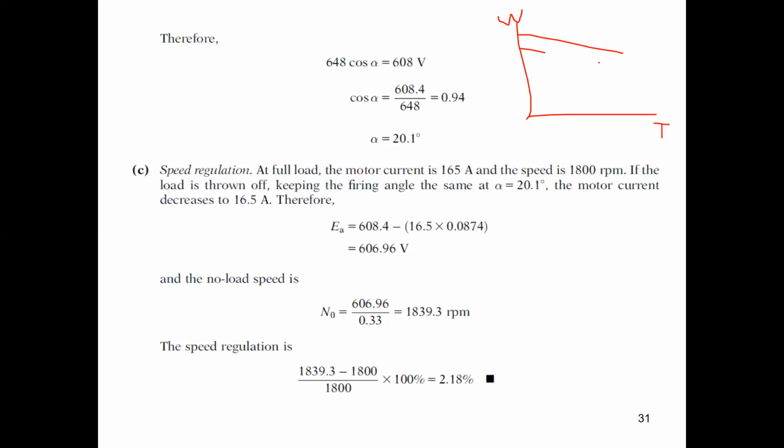So for any voltage curve, you will have different no load speed value. So we expect at different firing angles, we will have different no load speeds.